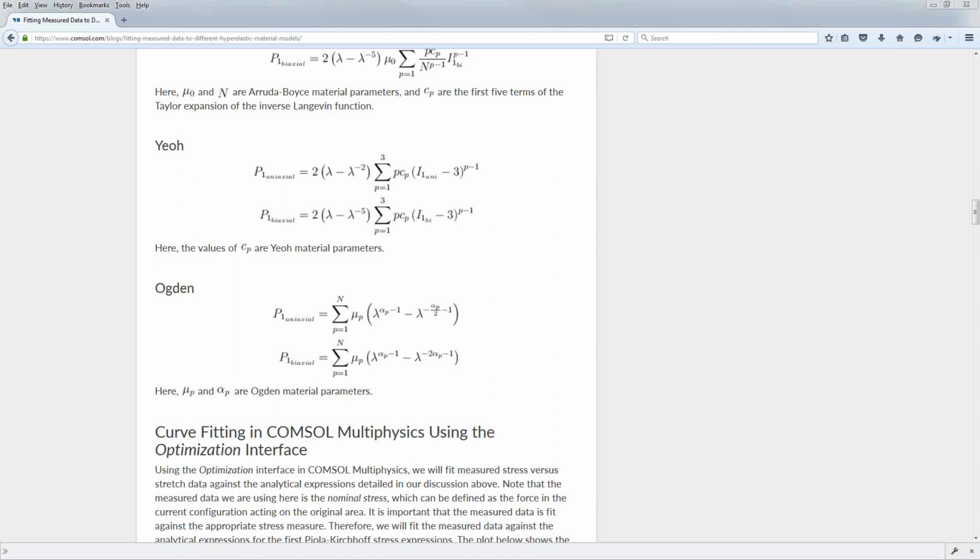So in material behavior, in the real world scenario where you're modeling a three-dimensional object subjected to stress strains in all directions, it will not be accurate and sometimes may fail because your material parameters are based on uniaxial test, but the simulation you're doing is not uniaxial. Yes, of course, if the simulation you're doing is primarily uniaxial, then that should be more or less good enough. But usually that's not the case.